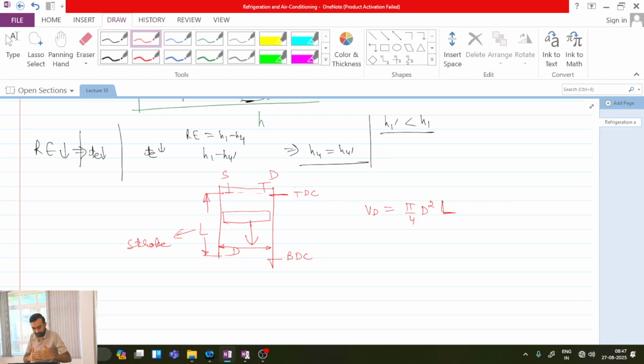Whenever you do the suction effect, the pressure within the system decreases. So when pressure within the system decreases, whatever the left fluid was there at the exit of the discharge stroke, its pressure was high. Whenever pressure will be decreasing, it will try to occupy more amount of volume. So it means it puts some penalty on the volume. As it is putting some penalty on the volume, the actual volume which is coming inside and going outside must be multiplied with one quantity which is called as volumetric efficiency.